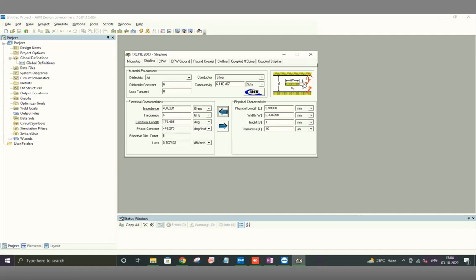One part is actually just obvious because as you increase this thickness, the gap is coming down a little bit. Right? So that's one part of it, which will affect the overall. But mostly it's going to control the losses. But typically for these kind of boards, I think the thickness of copper is about 35 microns.